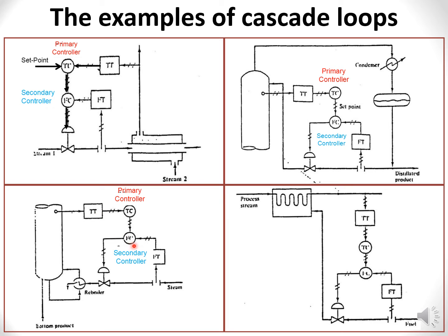Of course, more tuning needs to be done, because here we need a PID and here we need a P or PI. So two tunings. As I said, this is a quick, manual one, and this is a more rigorous, more important, accurate tuning to be done for the primary controller.